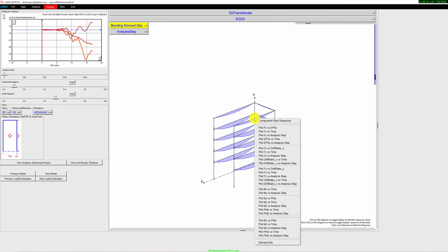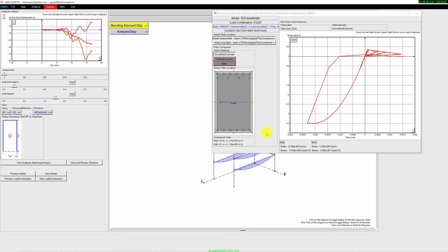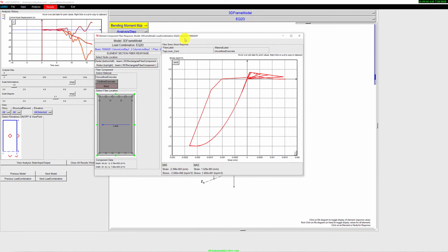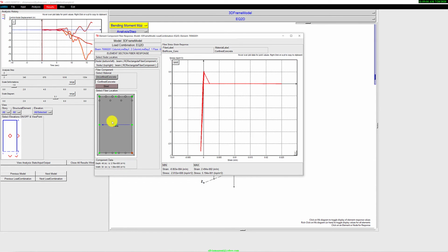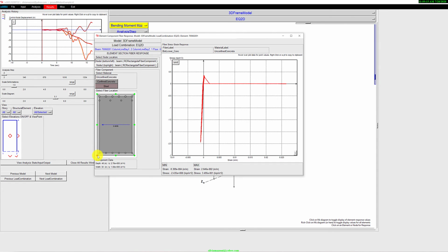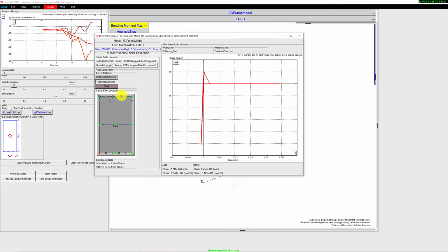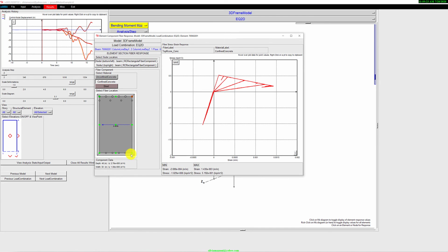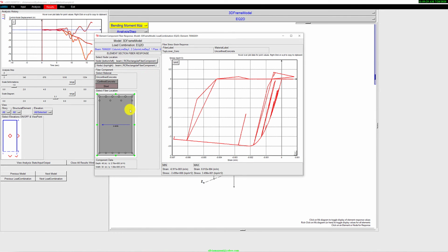What we want to find out is what's going on at our element level. Oh, look at that. Look at our concrete. It actually went through a full cycle here. Let's pick a fiber. So maybe this corner over here and this corner over here. Let's look at the very unconfined concrete on the outside. Let's look at the confined concrete on the inside. There's a lot of tension there. And maybe if we look at the other node, so this is at node J.